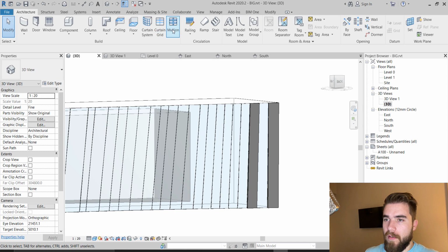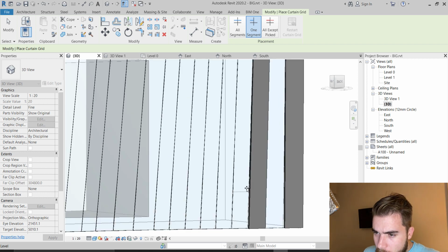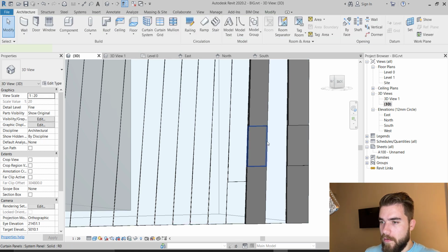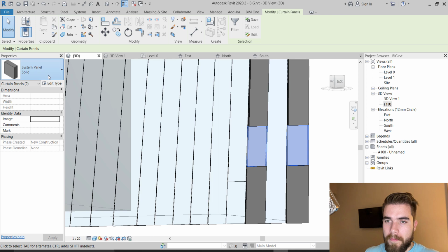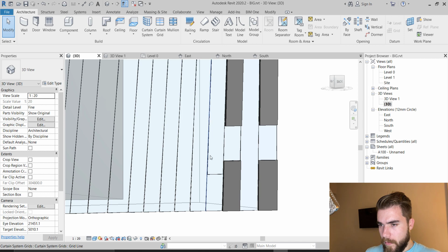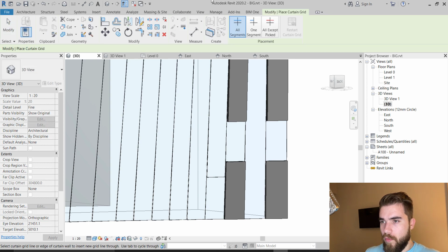And then we can go, okay, let's make our structure one grid line at a time. We select the one segment and we say, okay, here we want our panel, this is going to be glass, then from here to here is also going to be glass, and from here to here. So we change this to the glazed panel. And then we can, of course, create more of these one segments here. We can align them.